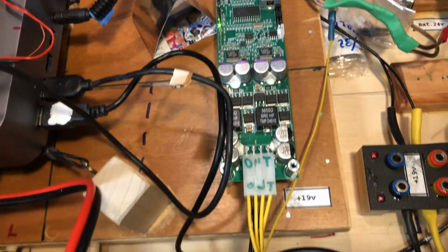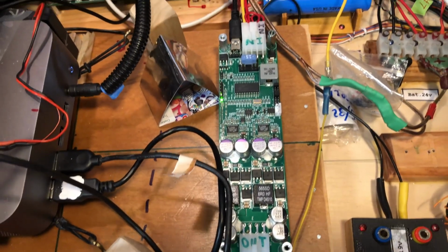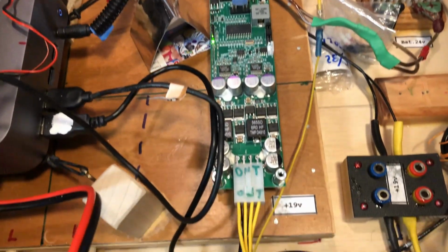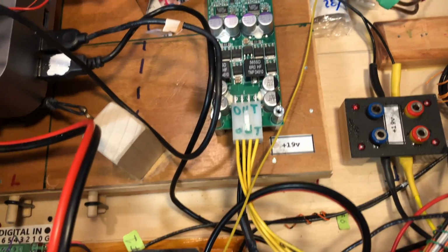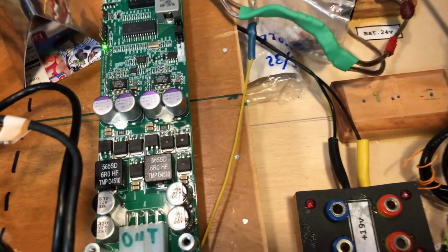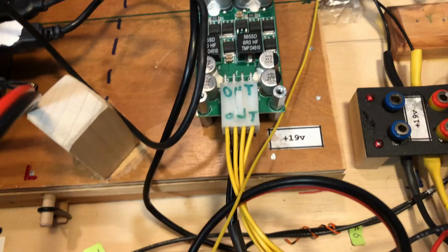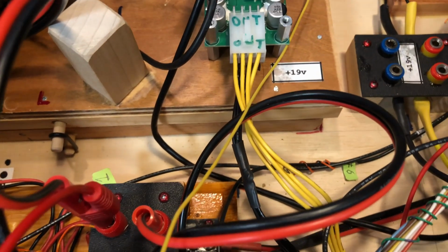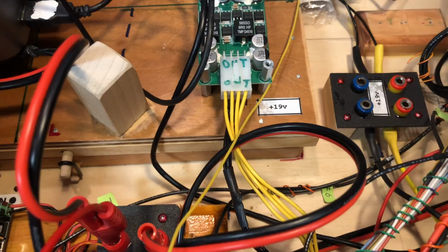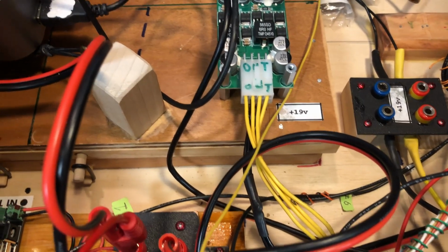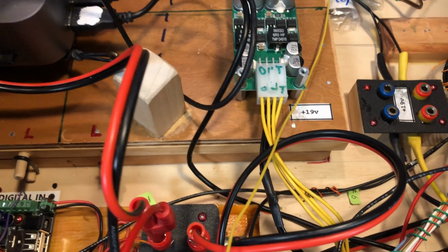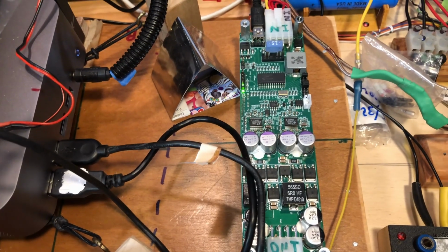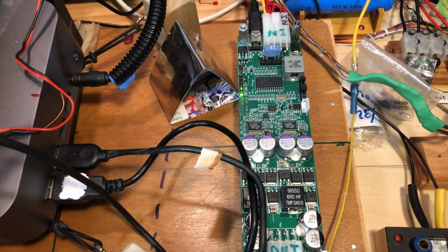Now this DC-DC converter is in what they call automotive mode, and it's got an extra wire coming out of it, that yellow wire right there. It's called ignition. And so you can control the power. That's supposed to go to the ignition of your car if you're running your computer in a car. But I'm not. I'm trying to run this thing off of the batteries that go through this DC-DC converter.